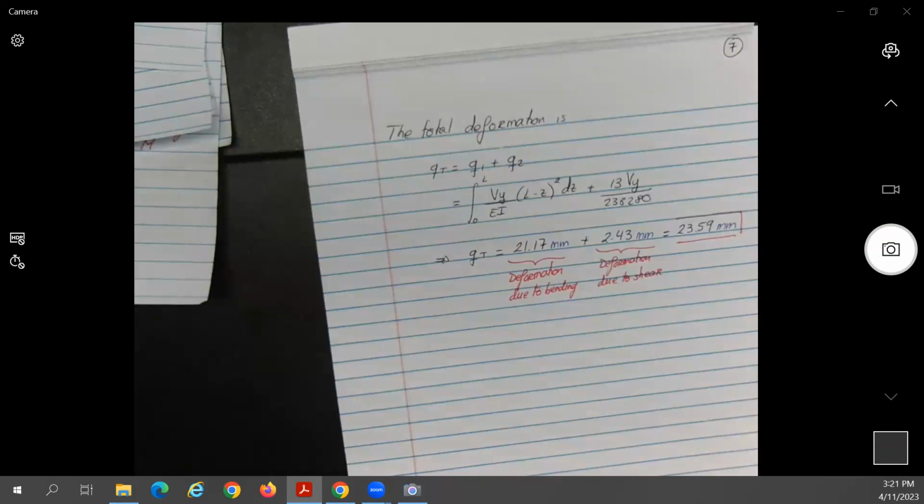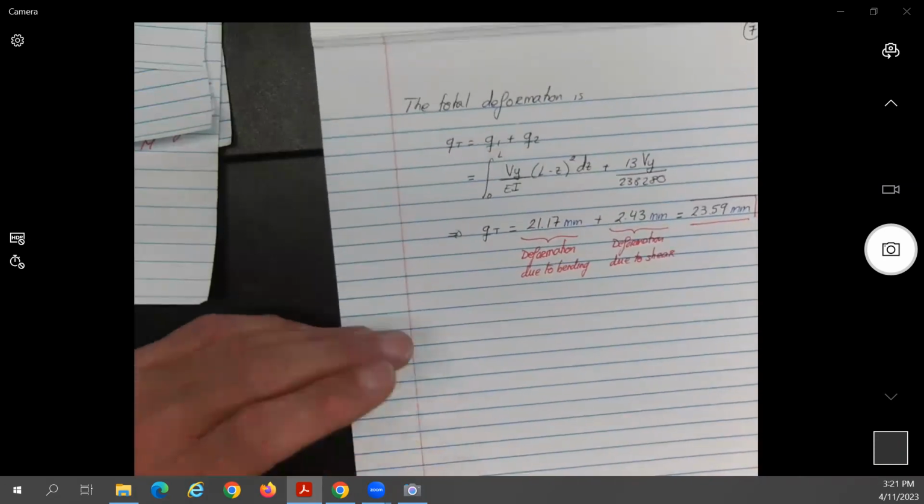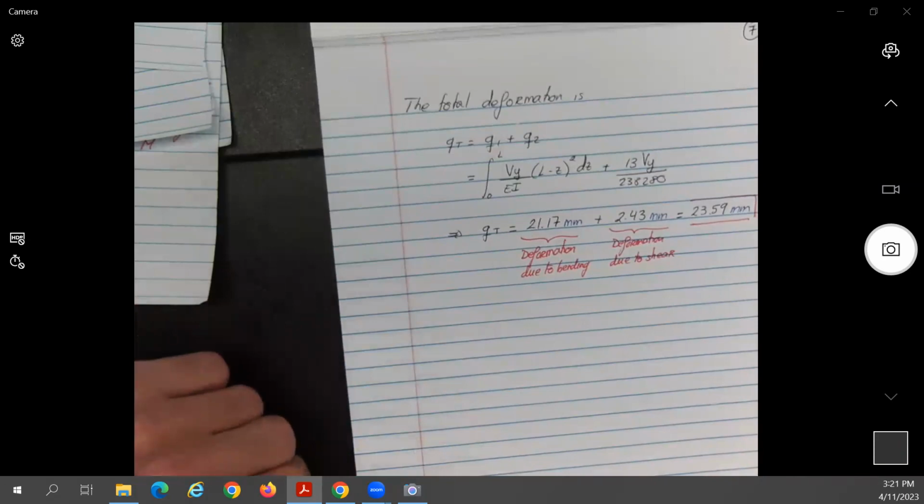So if you multiply the shear flow by the length, you have the total force that needs to be applied in that section. So you might know what is the minimum number of rivets that you need to have over there. Okay? And everything on an aircraft is made out of panels that are riveted, either the fuselage or the wings, no? Okay? So we'll do that next time, but basically you see why shear is so important. So obviously, you have a lot more rivets than you need to have. Why?